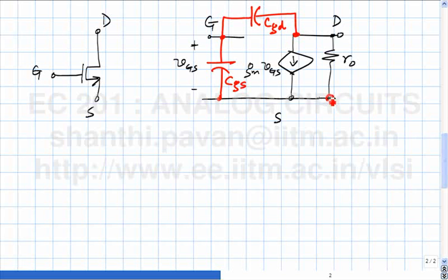there is a parasitic capacitance between what is called the bulk terminal of the MOSFET. I basically conned you when I told you that the MOSFET is a 3-terminal device. It's actually a 4-terminal device. Take for granted at this point that there is always a capacitance from the source to a terminal called the bulk of the transistor.